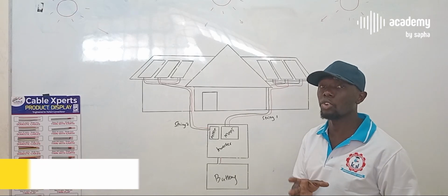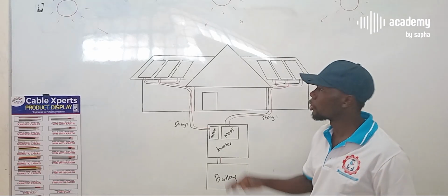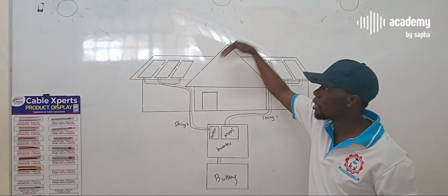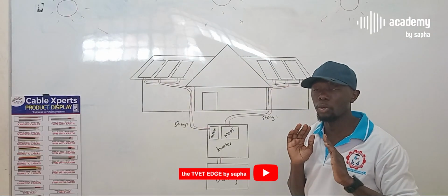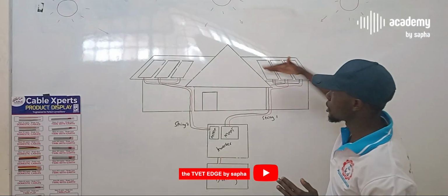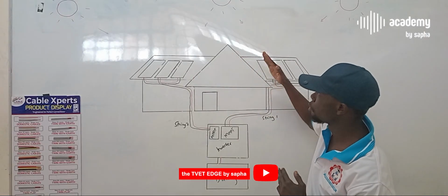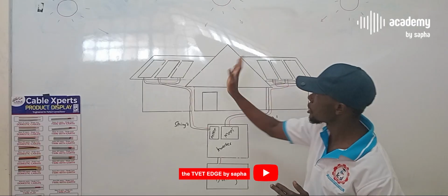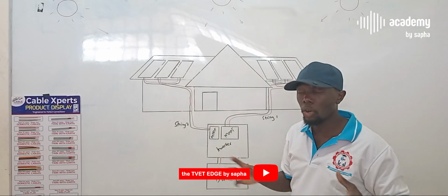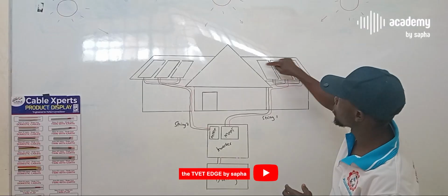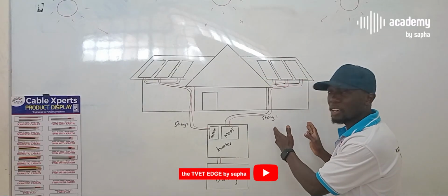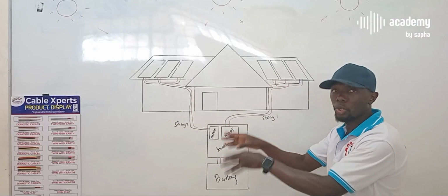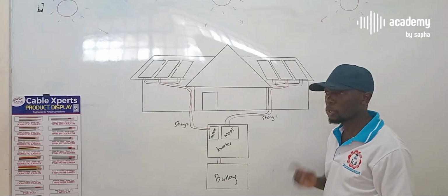You can buy charge controllers independently, have your panels configured on all the sections of the roof, and say these panels and the ones here can feed one MPPT outside the inverter, and then all of them push that power into the inverter. So that's what I wanted to say.